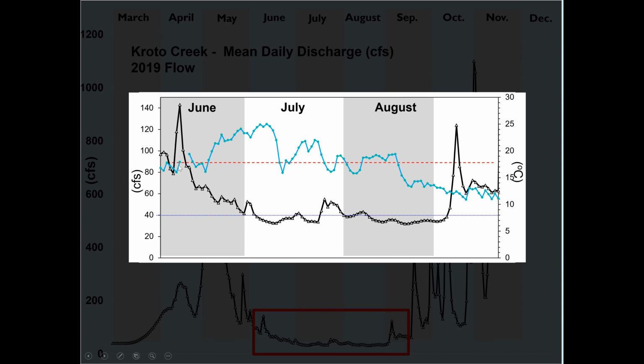And the temperature with those sunny days spiked as well. The blue line is showing that. And I got the red line there that's showing a threshold for the maximum temperature for juvenile salmon rearing. That's at 18 degrees Celsius, according to an EPA publication. But as Sean mentioned yesterday, those can be different for every stream and different for fish at different life stages and different settings.